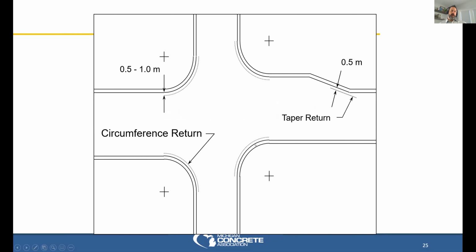And we recommend that around all of your curb returns, or the arcs at the corners here, as well as any beginning of a taper where you're adding a lane. This is just a construction line offset, so that we don't want joints to go through these areas, because those are areas where we'll have acute angles, triangular shaped slabs, and cracking if we just continue our regular joint pattern through those areas.